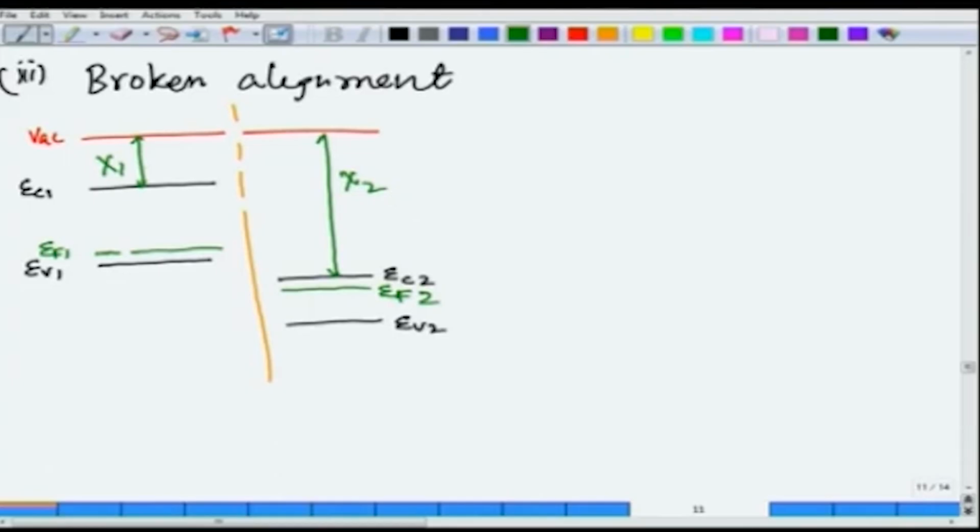What happens if you join them again? Remember, the way to do it is, imagine the material on the right, you lift it up so that the Fermi energy becomes equal. So that is what we do. Draw the Fermi energy, draw the junction. Always one material is on the left, so let us draw it completely. So, here it is, and we will just stay away from the interface; far away, the material does not change, it remains as is, and I am drawing the vacuum level also right here.